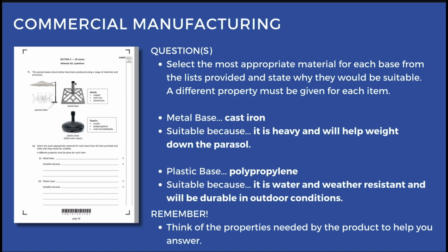Now it's suitable because it's heavy and it will help weigh down the parasol. As for the plastic base, acrylic would be too light and too brittle. Polypropylene, good flexibility and good weather resistance. Urea formaldehyde, durable but prone to cracking and only really used for electrical casings. So in this case it would be polypropylene, and it would be suitable because it's water and weather resistant, and that will make sure it's durable in outdoor conditions.